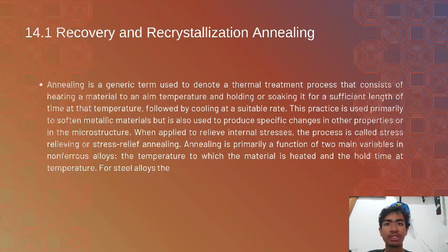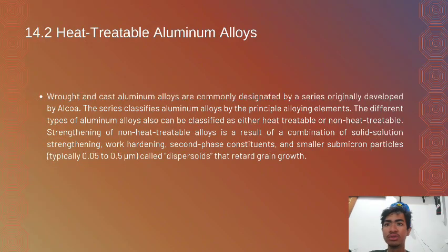For example, the electrical resistivity of an alloy is typically increased by cold working, but can be recovered before annealing has a significant effect on hardness. 14.2 Heat treatable aluminum alloy.